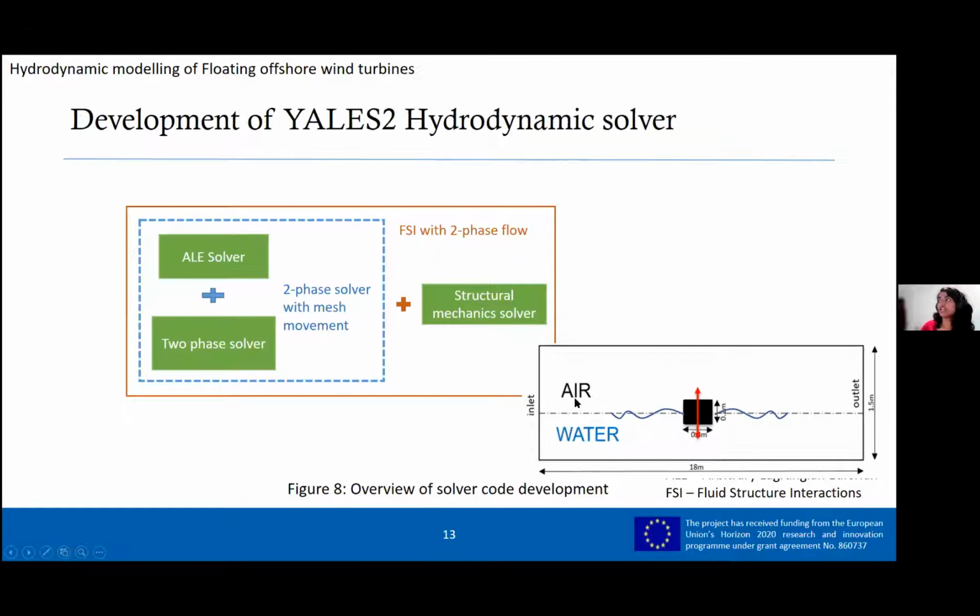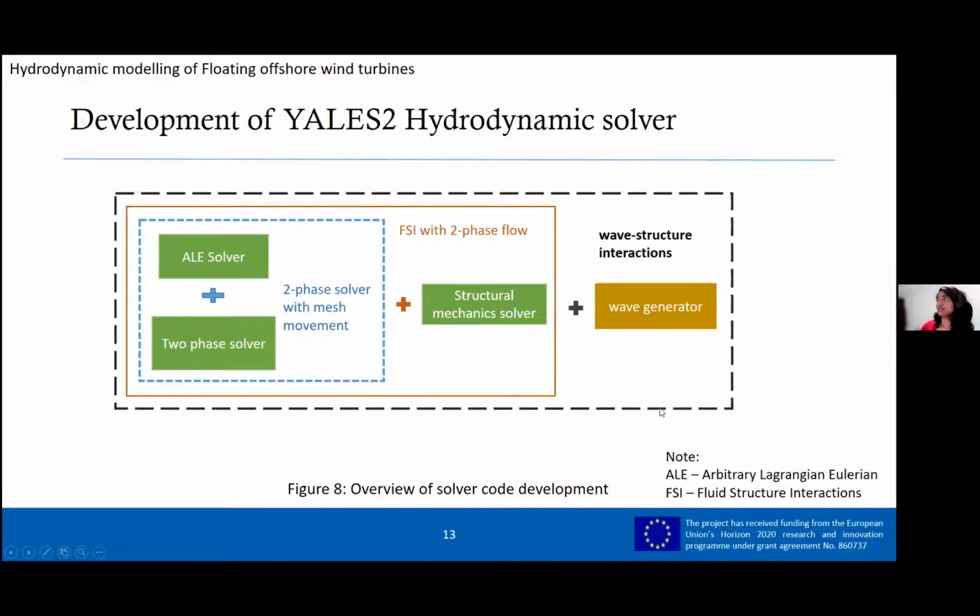the screen. It's a very simple setup with an air and water interface here and a 2D box performing heave in this particular case, but we can perform any other free decay simulations in heave, surge, or sway. And the project right now is at this stage of validation. After the validation, the idea is to add a wave maker module or a wave generator module to understand the wave structure interactions overall for the platform.